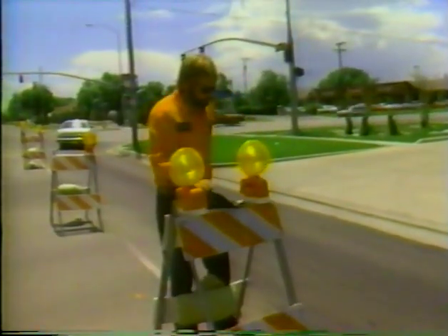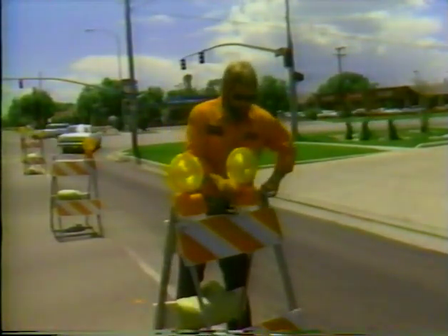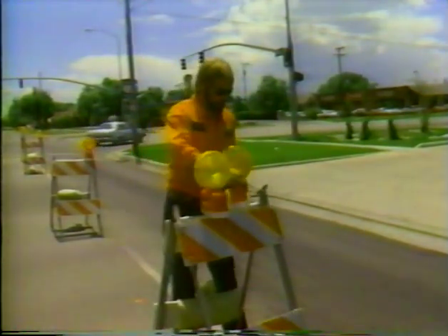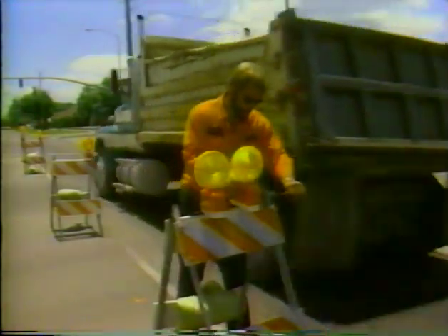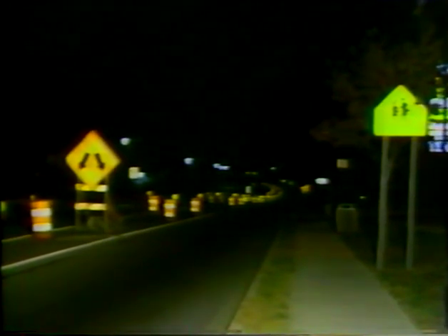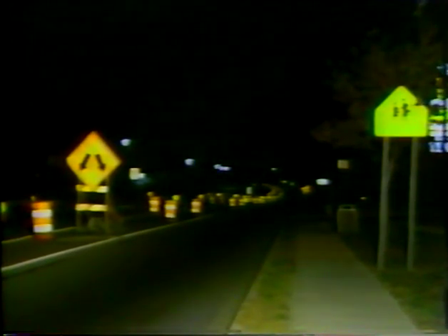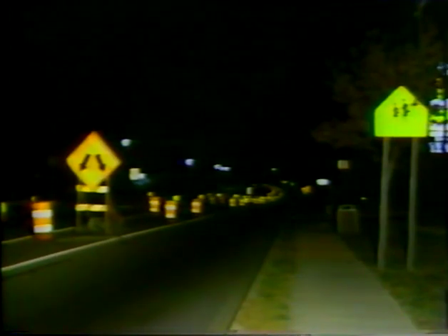The contractor should replace bulbs and batteries on a regular basis and respond immediately to emergency maintenance requests. Some agencies have established minimum levels of maintenance of warning lights. They may require a certain percentage of all lights to be working. When the lights fall below that level of acceptable performance, the contractor is notified of the need for service. But when there is no prescribed level of maintenance, you have to make a judgment based upon what a driver is likely to see and conclude.